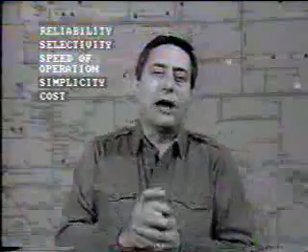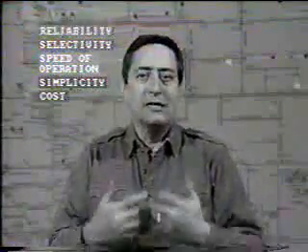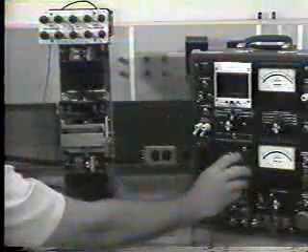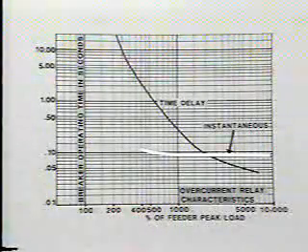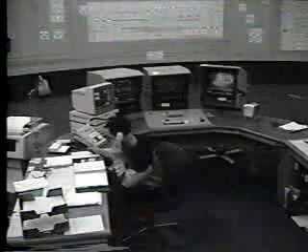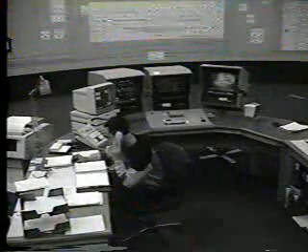First, we have to rely upon the relay or relay system operating correctly. That is, to operate and trip out the faulty circuit when it's necessary to do so. The reliability of the relay is tested by inputting current and voltage which simulate fault conditions. The time of operation can be measured in relation to the degree of fault condition. A second aspect of reliability is that the system must not trip out during normal operation.